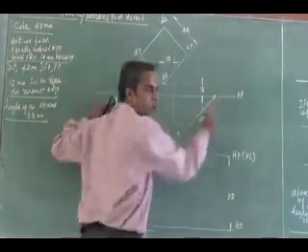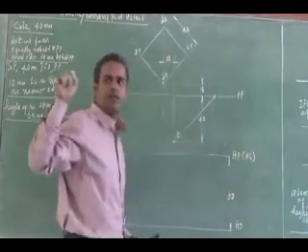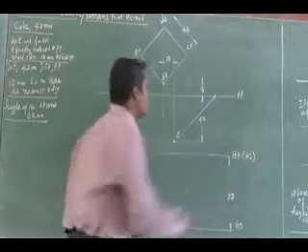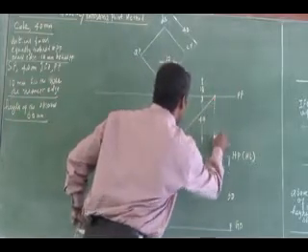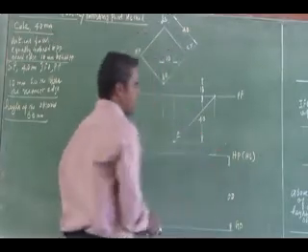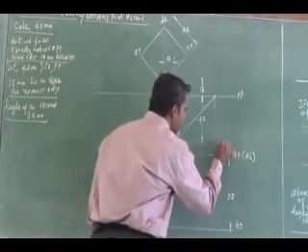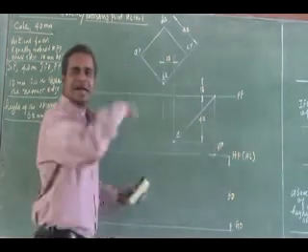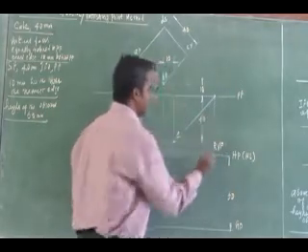So from this location, you drop that, project that to where I have to get the vanishing point on the horizon plane. You project that location to the horizon plane. So this location is my vanishing point location. What vanishing point is this? Right side vanishing point. So this is RVP, the right vanishing point.